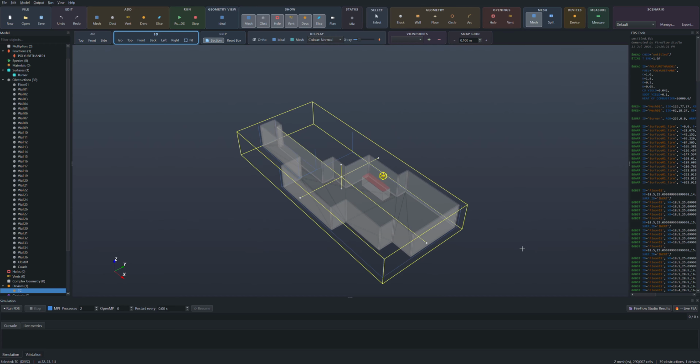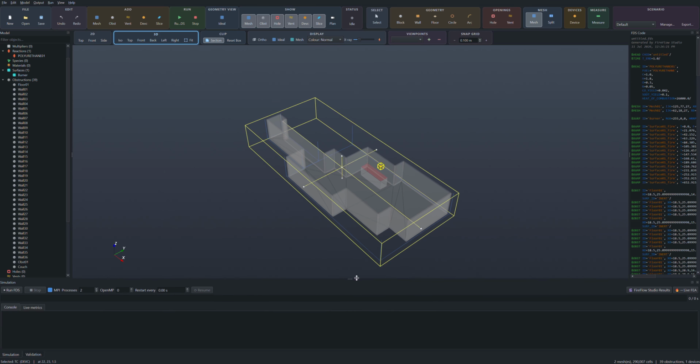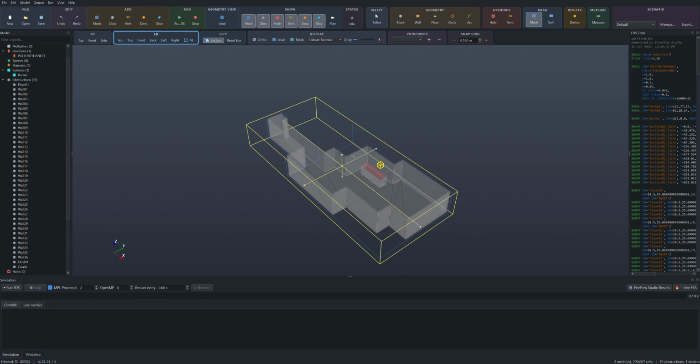the next feature I want to show you is the ability to model both gas phase and solid phase within a single application, right? So all of that gets modeled within the software. It's absolutely fantastic. But to enable that, we need to set our boundary conditions as AST, adiabatic surface temperatures. We have to activate that so that we have a boundary condition to feed into our finite element model.